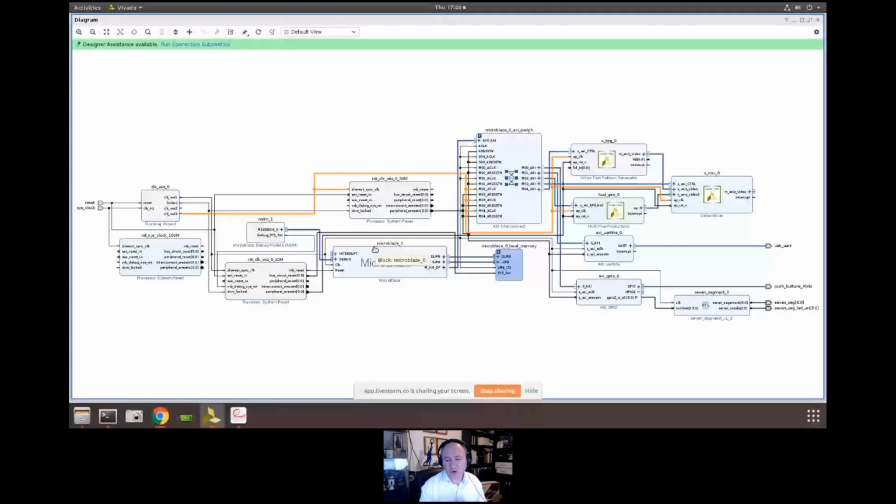We're going to be using a 4-bit resolution really at the end of the day for each color. So 4 red, 4 green, 4 blue. But first, what we need is this AXI stream interface, and the data represents the video coming through as an AXI stream, which is pretty much just a continuous stream of data.